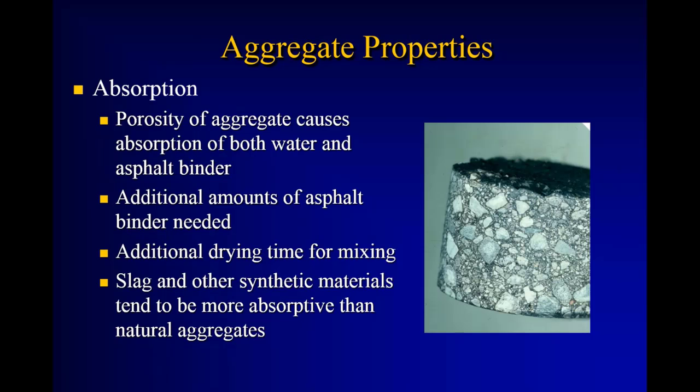but it also helps with some of the other properties of the mix. Absorption is a biggie in our part of the world in North Dakota. All aggregate, natural aggregate basically, is porous. It will absorb water. If you've done concrete mixes, you know that as well. Absorbed versus free water for running your water cement ratios. But if it absorbs water, it will also absorb asphalt.